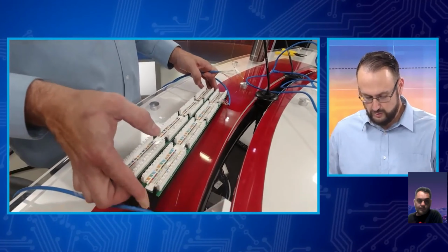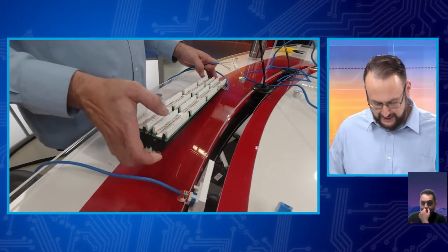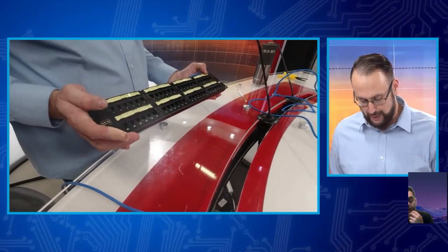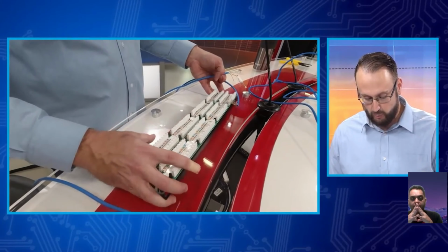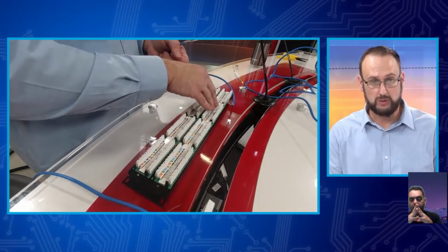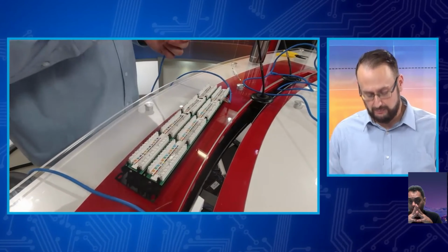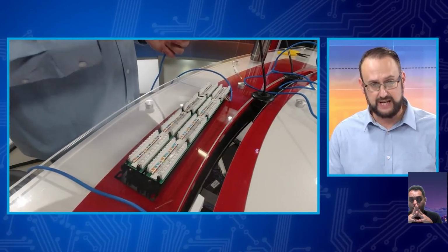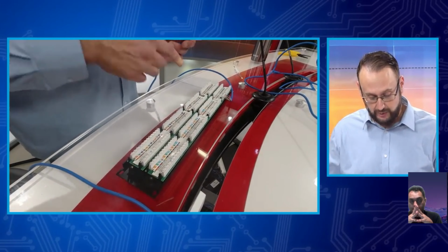In this video, we'd like to demonstrate how to wire a patch panel. All right, so in order to wire your patch panel, on the back of the patch panel we determine what the wiring scheme is, and typically what we're going to be using here is 568A for the inside of the wall.